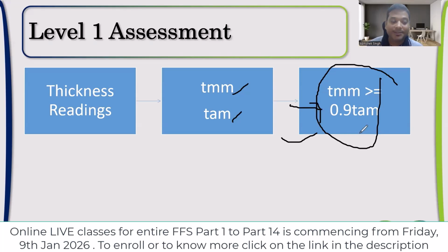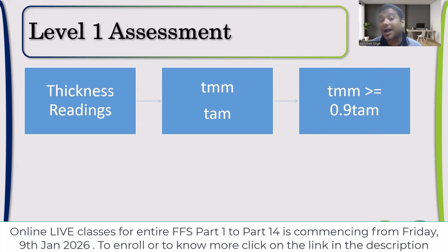Okay, so that is what it indicates. That is a very good hard boundary for Part 4 and Part 5. So if it is not able to meet this criteria, I'll directly jump to Part 5. I'll not go further and try to analyze by Part 4. It's not a general metal loss now. It is becoming a local metal loss if it is not meeting that criteria.